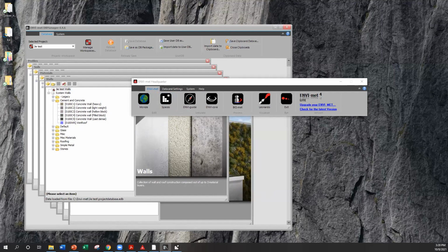It gives you the resolution and it tells you on each Z level what is the height of each Z grid and what is the highest grid. In my model, my highest level is the 70th grid, which is pretty enough. And it will give you some check results. Please check this and modify your model until there are no warnings here. As it says, space between buildings and model edge should be larger. So I need to give more space to make my model wider.